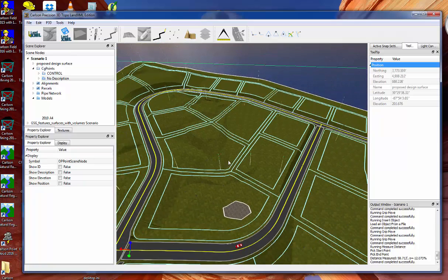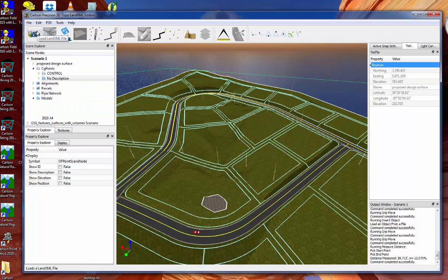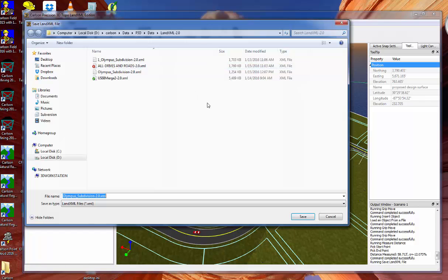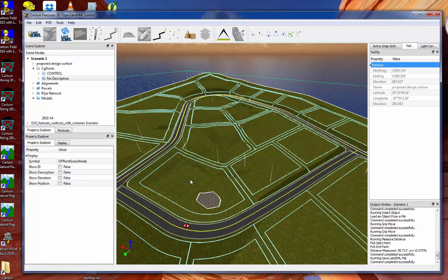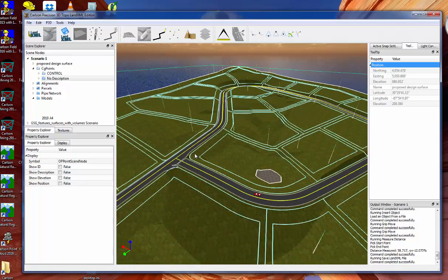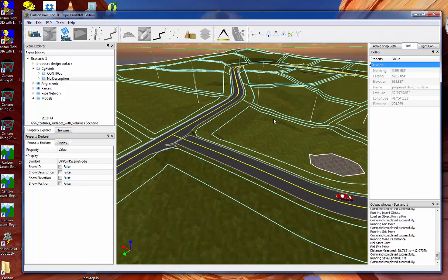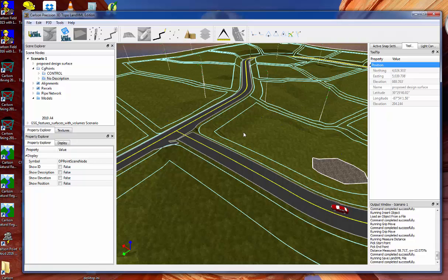And we could basically now take this file and save it as a LandXML 2.0 file. Now, since this is an initial release, what we export when we save a LandXML 2.0 file is primarily the surface data and the multi-textures. We also export all the COGO points. At this time, we do not export any polyline data yet, because the LandXML schema is very large when it comes to all the different geometry types, and we have fantastic support for importing all of those types, including spirals, but we're working on adding additional application support to be able to round trip completely.